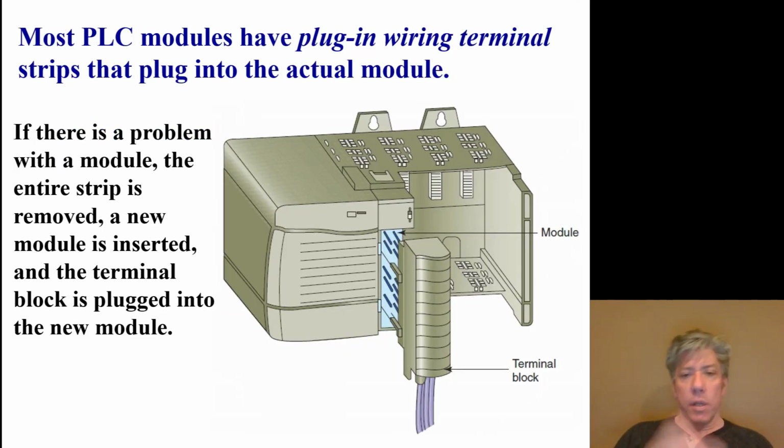And then here's a really important feature of every PLC I've ever seen, and that is plug-in wiring terminals. If you think about it, if you've got a module with even 8 different inputs, what if that module goes bad? What do you want to do? Well, you want to replace it. Do you really want to unwire 8 wires plus probably 2 or 3 that are required as well? So you've got 11 or 12 wires, and you're trying to figure out where they go once you get the new card in. Well, the whole idea behind a PLC is to have something rugged and reliable, and when it's not, have it very serviceable.